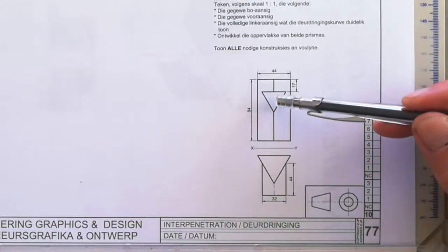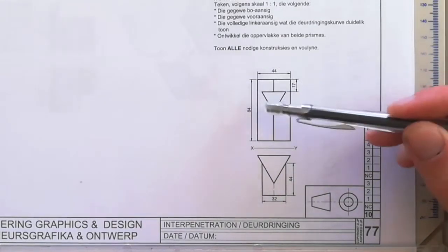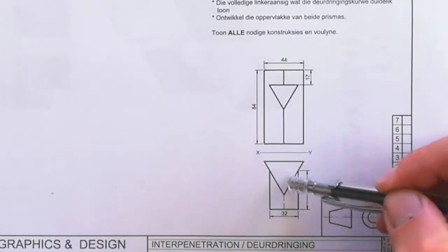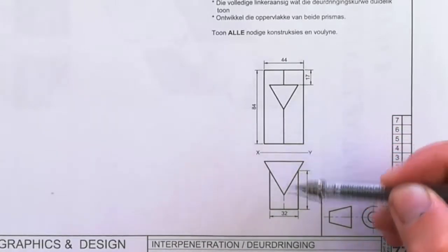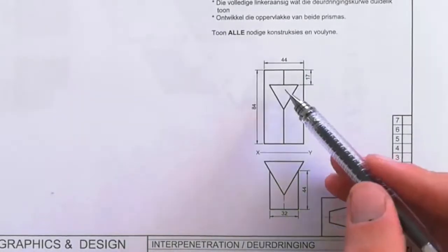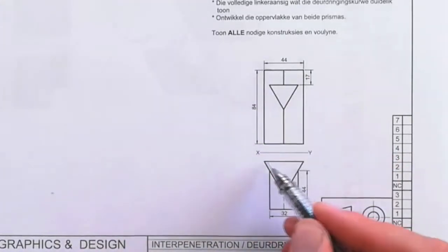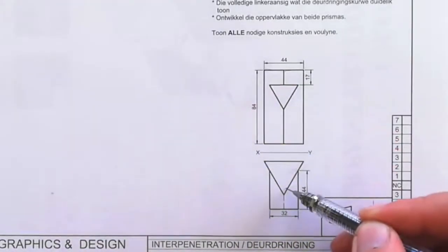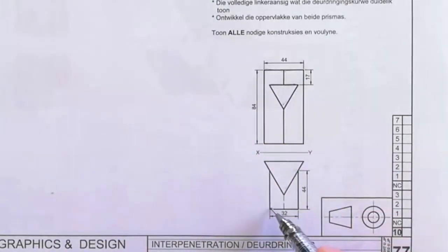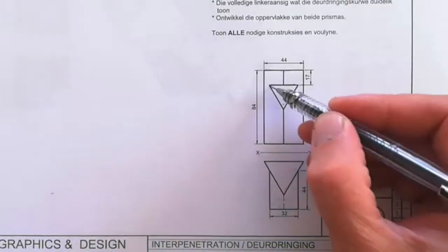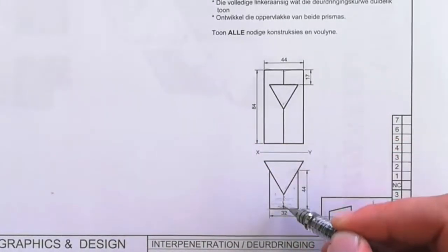They've given us here a front view and a top view. These are two right equilateral triangle prisms that fit to shape around each other, and the axes of both of them are lying in a common vertical plane. So there you can see in my front view, this side here is going to be this here. That side is going to be this side here. And this triangle, the top of it is actually this surface here, and then those two lines going down go to the center line. That corner there is actually this hidden detail here.